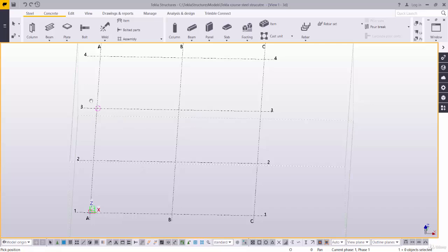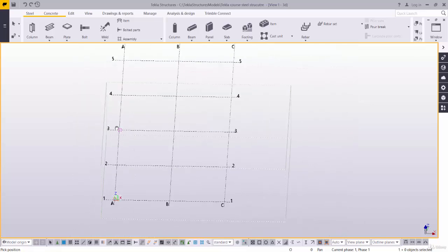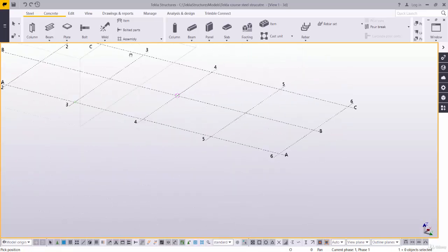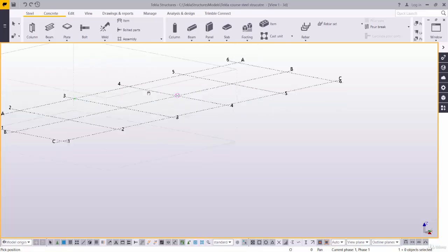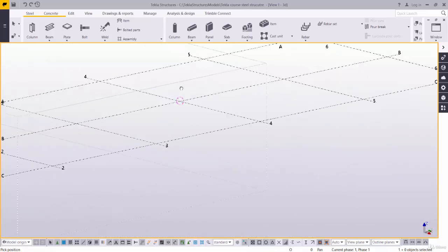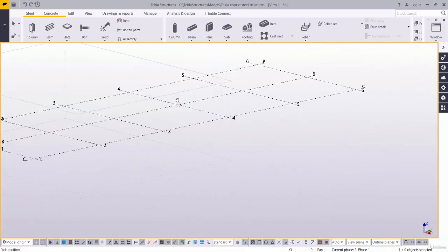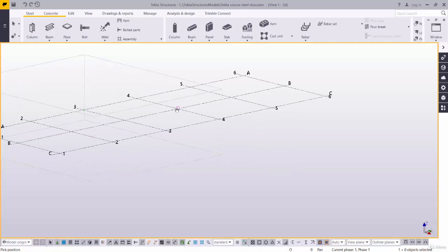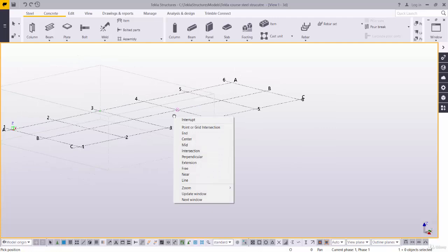We can change the location of this point by clicking Ctrl, then R, then the new location. We can use this option if we want to rotate about a point, a joint, or a structural element, to get a clearer display of this element. So we can change the center point of rotation by clicking Ctrl plus R.